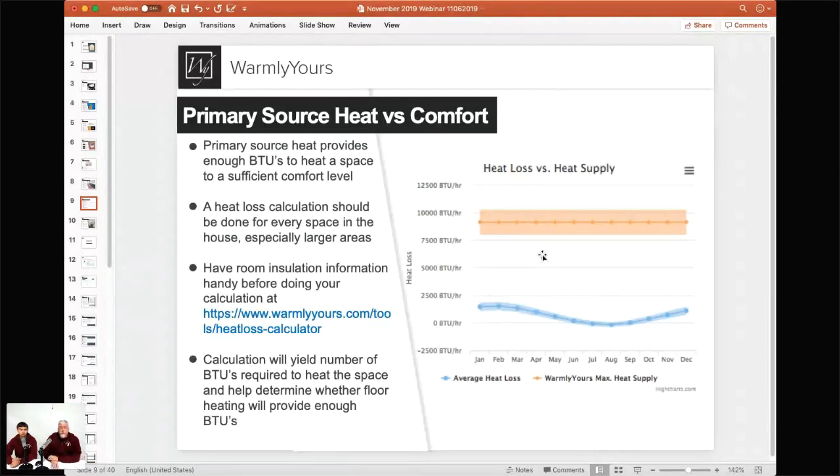And just to share more information with Tracy, all of our thermostats have a floor temperature limit setting. For example, you want to heat that room to a particular temperature, but you just don't want to stand on that floor at 100 degrees. You can always limit it at 90, limit it at 85, kind of put your own restrictor plate there, just because you don't want that floor to be running too hot. Right, so it's always possible. You don't need to stand on a 100-degree floor to make your room warm. What we're trying to get across is that a room that has a tile floor may make the room nice and warm.